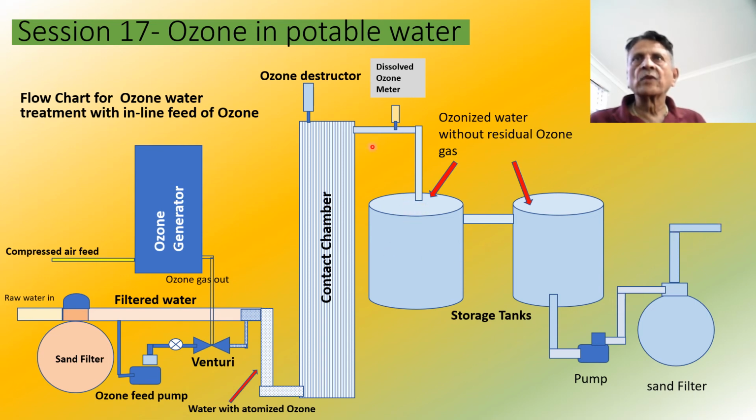Now, if the water is directly used for community purposes, then obviously it is further added with chlorine and ammonia to ensure all the distribution channels are clean and that water will have sufficient residual chlorine till it comes out to the tap.